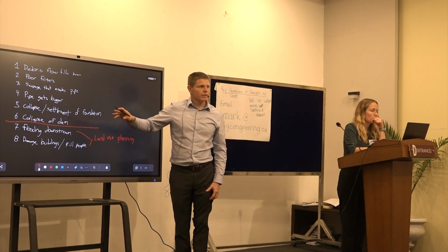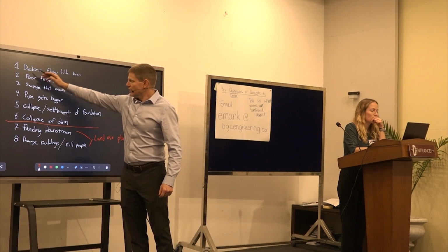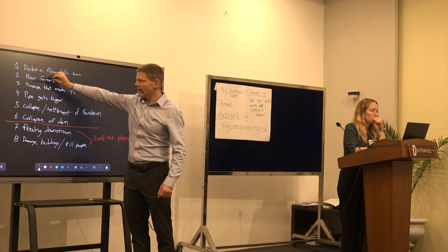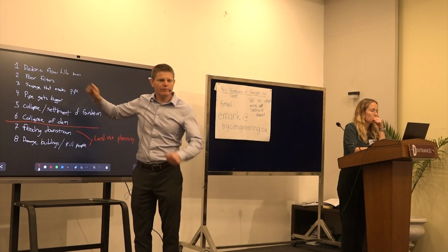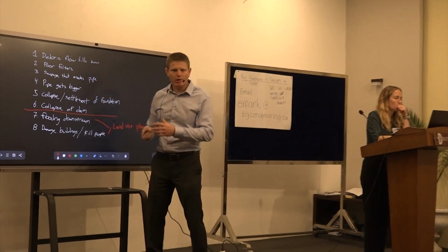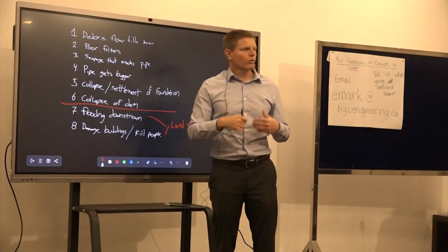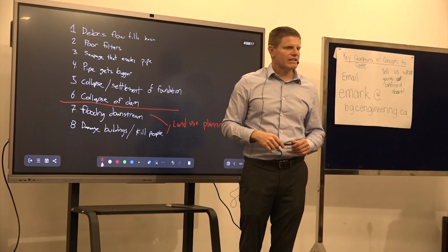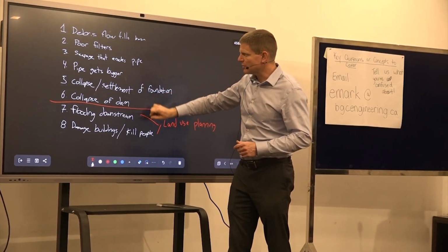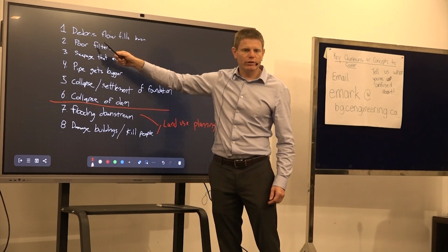The filters. Right? In order for this piping erosion to occur, we have to have a poor filter. Because if we have a good filter, then the process never begins. So right now, if we're in the process of designing our structure, we can say, if we want to prevent all of this from occurring, we must have good filters.